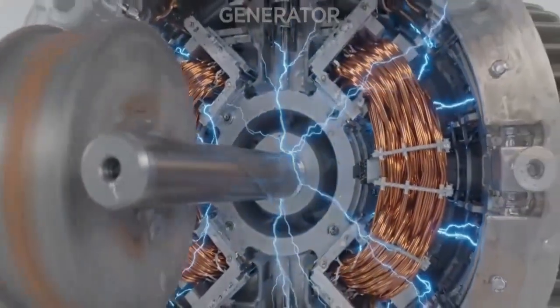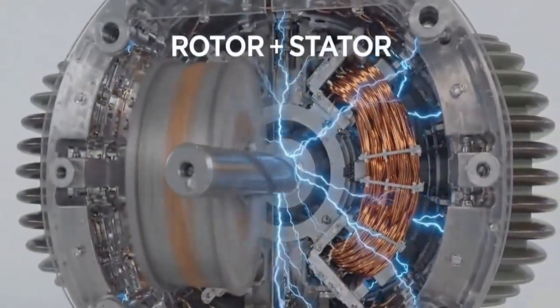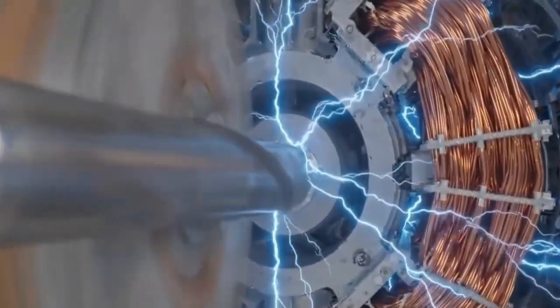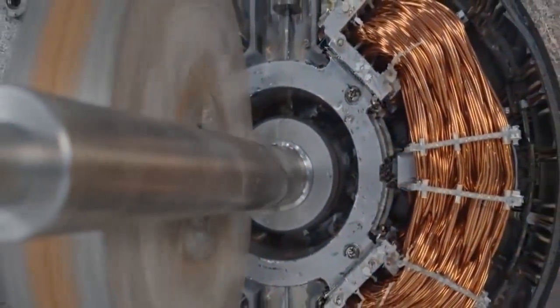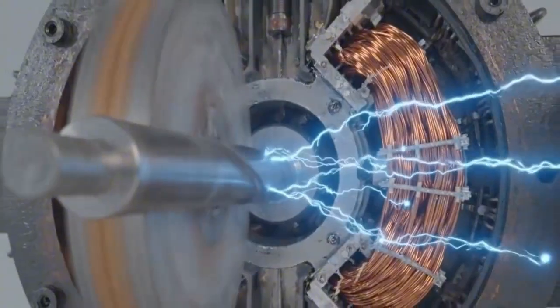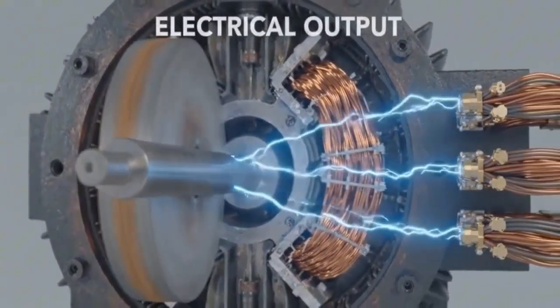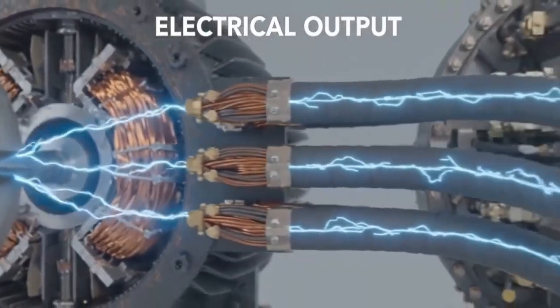Some modern turbines remove the gearbox entirely and use a direct drive design with a much larger generator. In a direct drive system, the rotor connects more directly to the generator, reducing mechanical parts but increasing generator size. In this video, we return to the geared drivetrain because it clearly shows how energy moves through the system.